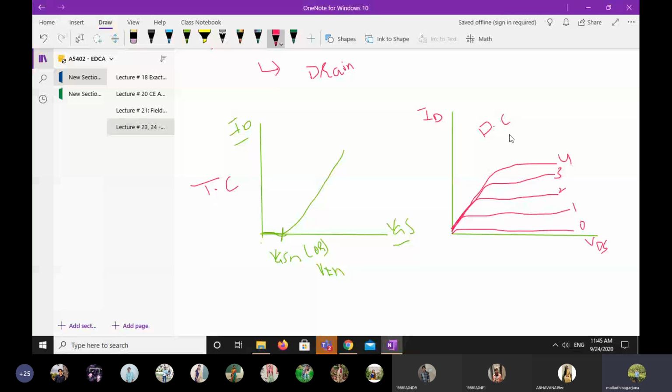See, from the characteristic, if you take VGS equal to 4, let us say, and you are decreasing the VDS in this direction, see the current, it is coming down, right? Yes, sir. So if we increase VGS and decrease VDS, current will decrease. If you make VDS equal to 0, the ID completely becomes 0. If VDS is completely 0, and ID also 0, this is the origin point, right? Okay.